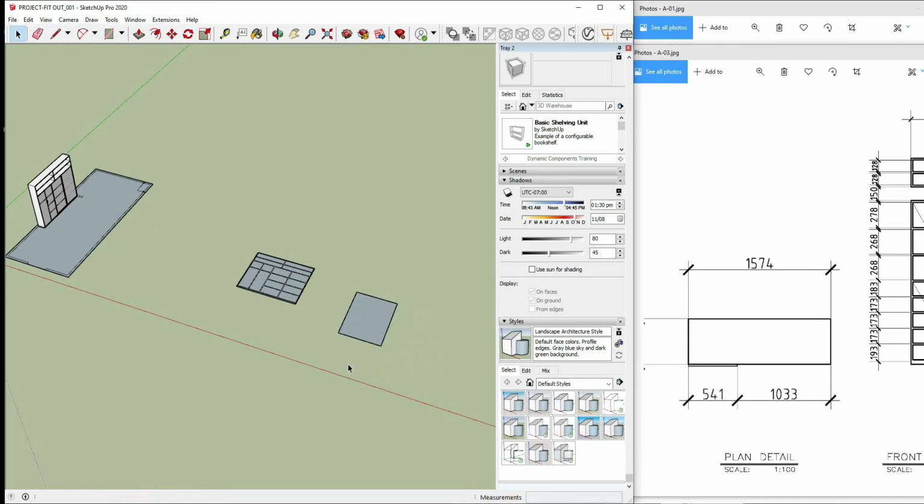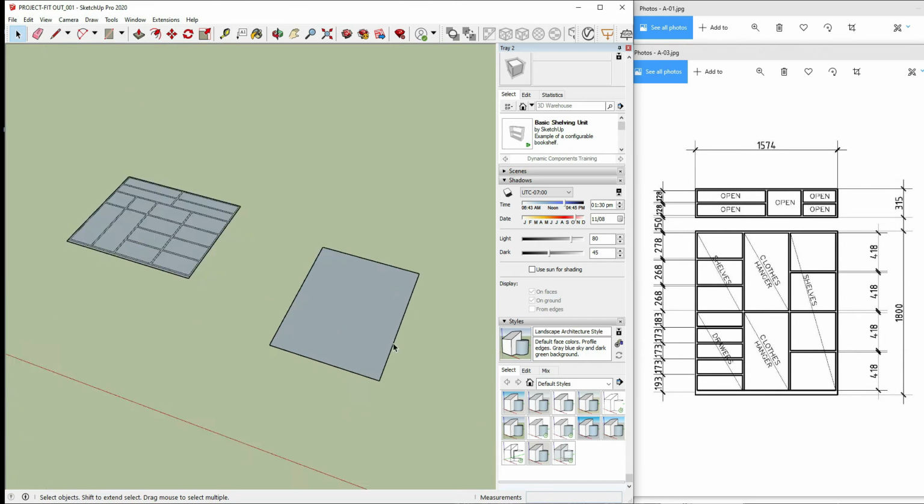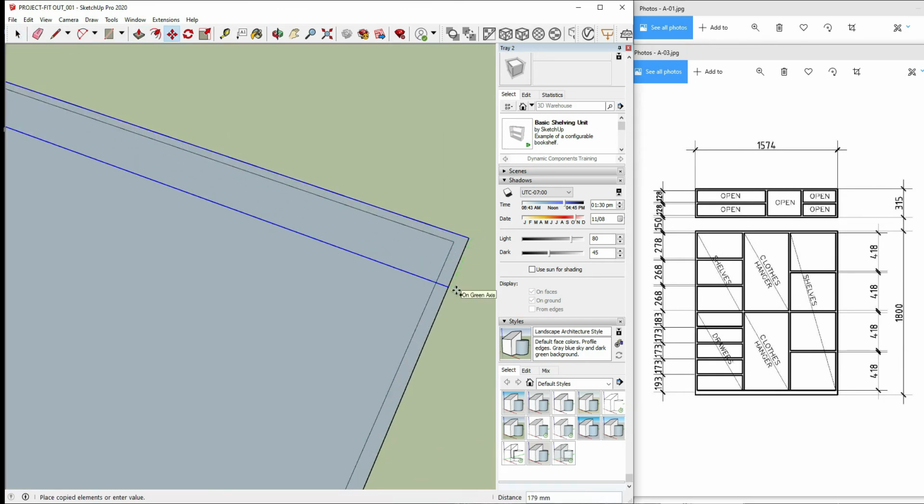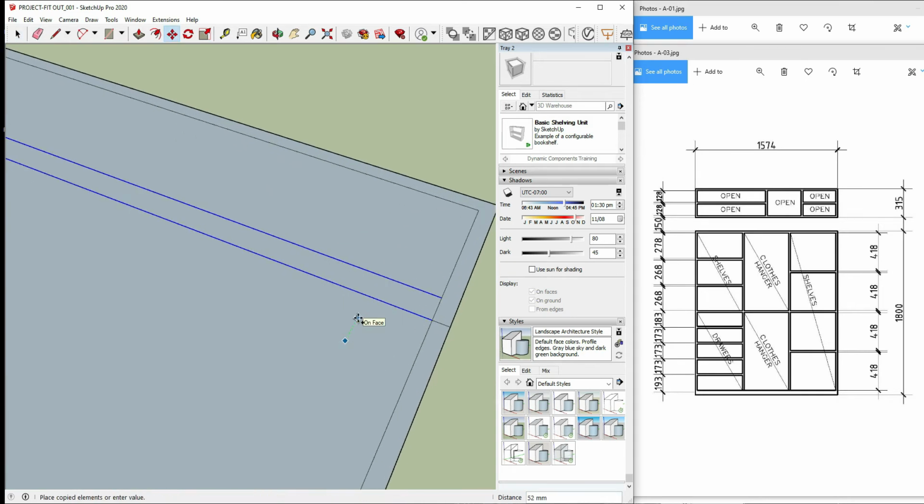The same procedure that we did. First we create the layout, a rectangle with the given dimensions from the right portion of the screen. We input the data and the measurements located at the lower right portion of the SketchUp interface.